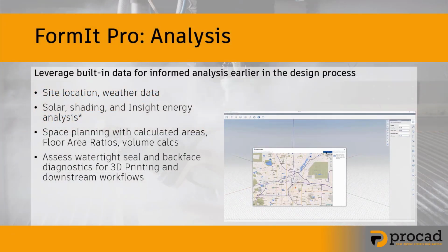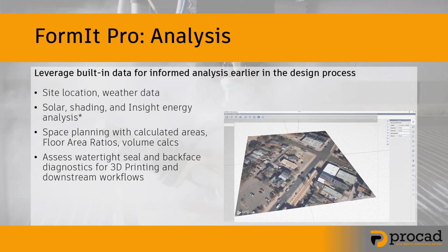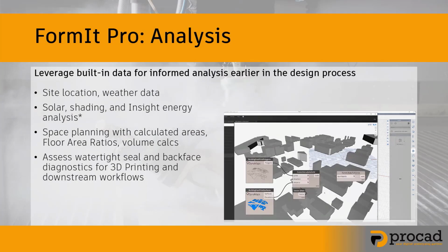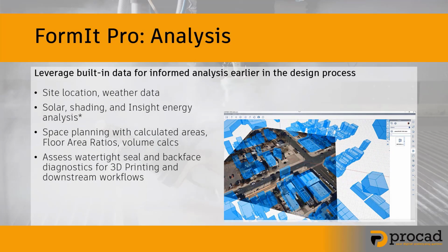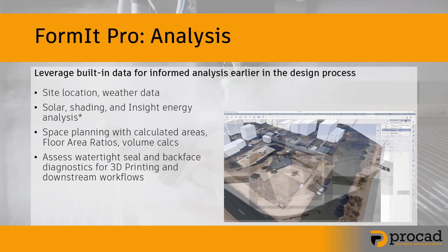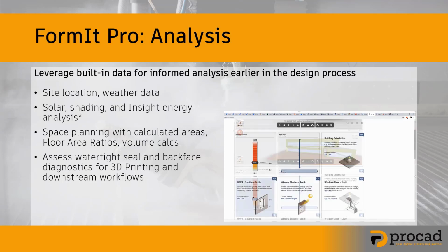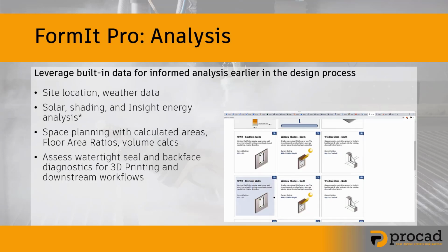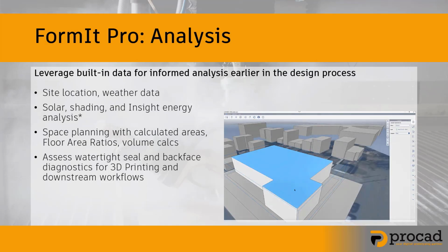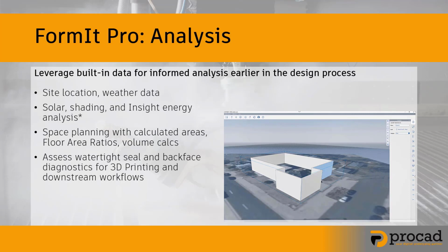Setting the location allows you to get real-time weather data from local weather stations, which can be used for shadow studies, solar heat gain analysis, and for energy optimization modelling through Insight. Each form notes its area, and along with the overall site area, floor area ratio and floor areas are calculated and always up to date as the design changes.